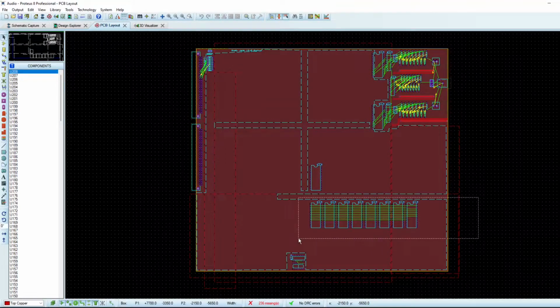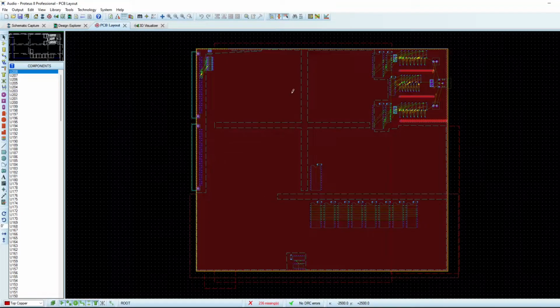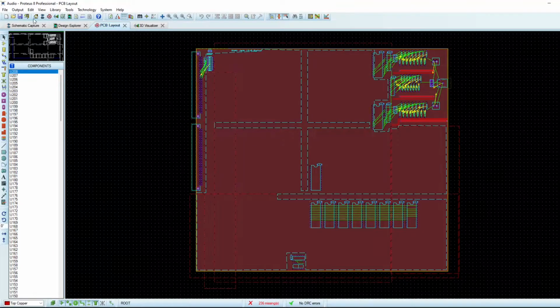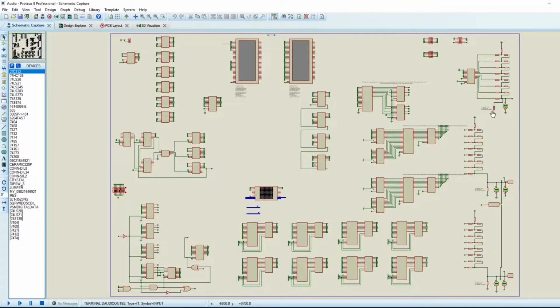This is the 64 kilobytes of memory laid out here, and this is the EEPROM for the common volume mixing. I'm allowing the autoplacer to select the position for all of the other logic ICs. What I found was that I had to exclude some areas of the board to allow enough routing between all of the different sections, and the autoplacer pretty much places everything quite well. But this is the common logic.